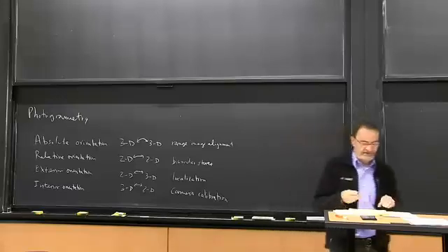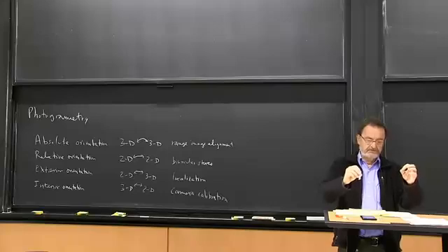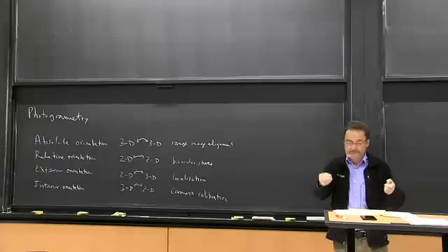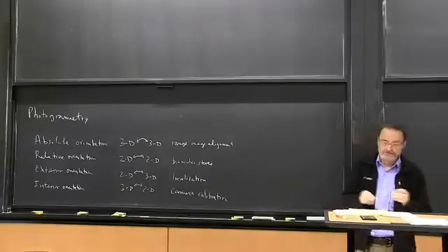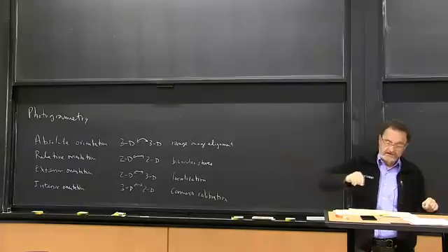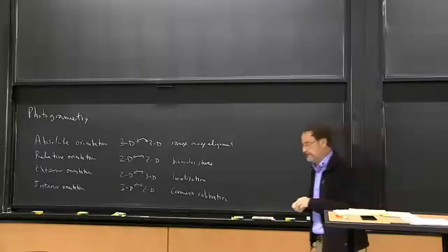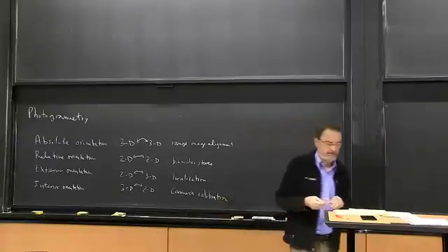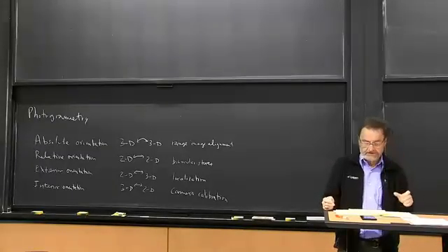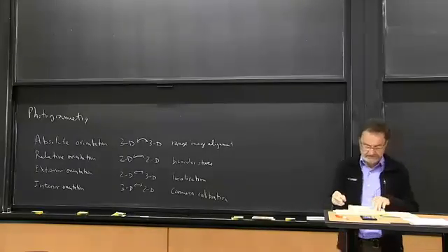And in order to plot the map, there would be an artificial point where you've introduced two points in the two images the person's looking at, and their position determines the height. So the person basically places that artificial point on the surface they see and moves it around at that height, thereby creating a contour. And of course we don't do that anymore. It's all now automated using correlation and convolution. But before we do that, we need to figure out how the cameras relate to each other.